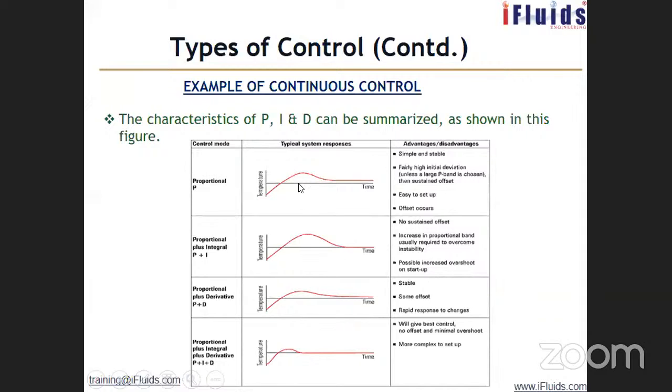You can see the difference here. Here the overshoot is more. Usually what the controller does, it takes some extra action, and then brings the controlled variable to the required set point by overshooting and trying to achieve it in a shorter time. So that is what you can see, more increase here, more difference here.